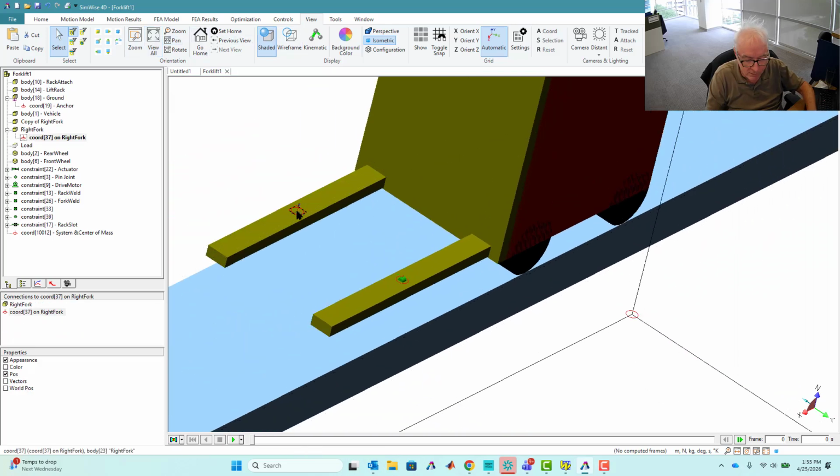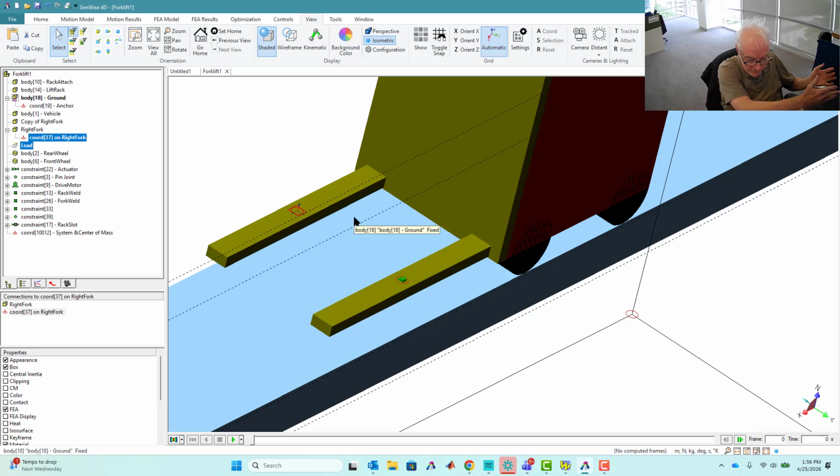All right, let's do the same thing, or let's create the joint here. And what I'm really doing is constructing the idea of a simply supported beam, right? It means that all I'm really asking this frame to do, the joint that we're going to put here, is not allow it to rotate according to that revolute axis. Now, why would I do that? Well, it means that we can measure the loads associated with each. And as we put asymmetric loads, and as we go on trajectories of motion for the vehicle where it does turns, that load will get distributed properly between the two. So that's all I'm going to do to explain it right now. Certainly if it's confusing, post questions and I'll happily respond to it.